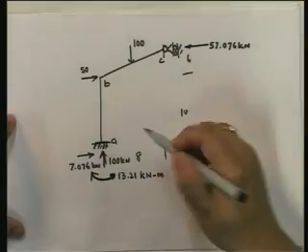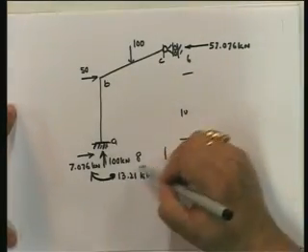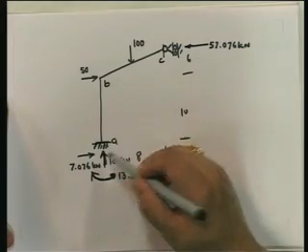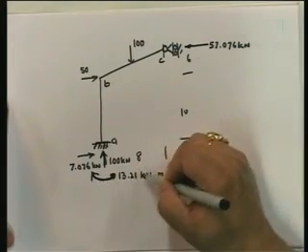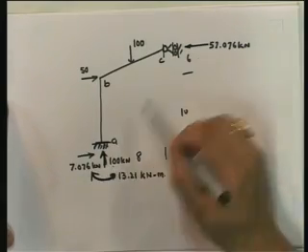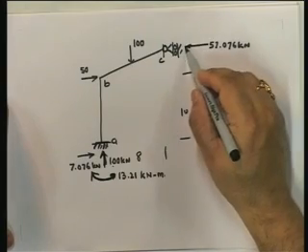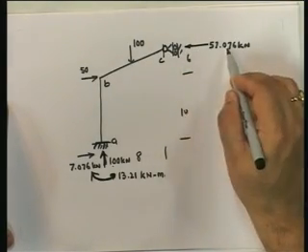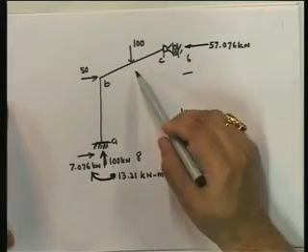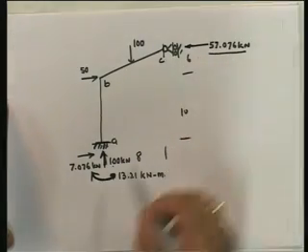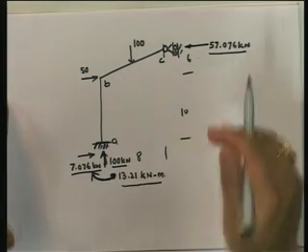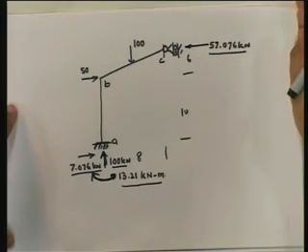Once I have the support reactions, this becomes a statically determinate structure, and I can draw the shear force and bending moment diagram for this. Okay, and if I do that, this is clockwise 13.21, this is 7.06, 100. Since this is a roller, the entire 100 comes here, and here, since it's a hinge, there is no moment, there is only 57. So far, the structure is more flexible and the support reactions are less. In other words, if serviceability is not a criterion, making the structure more flexible by removing a restraint of support seems to make the structure much better. However, let's look at